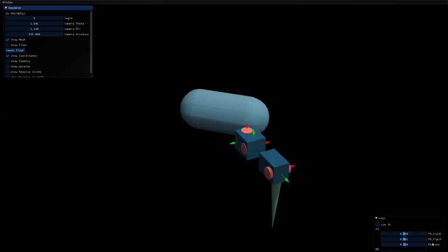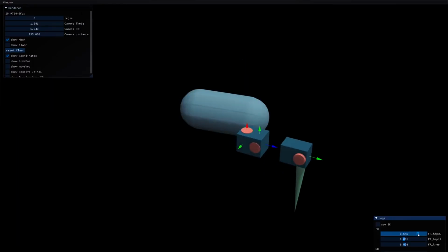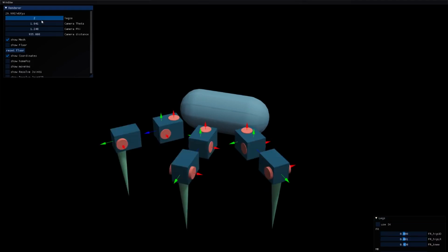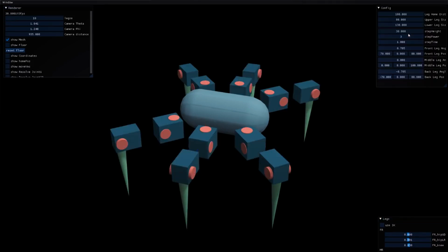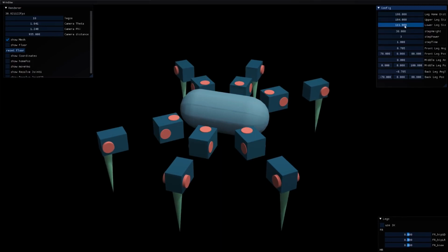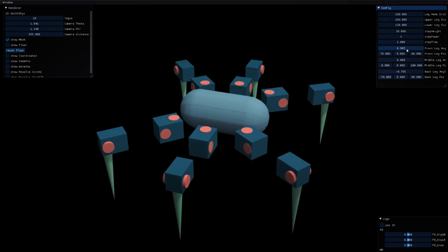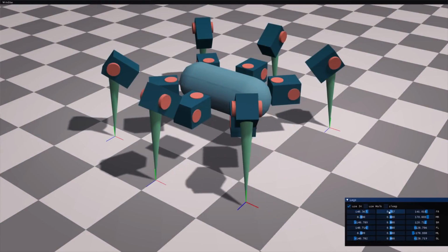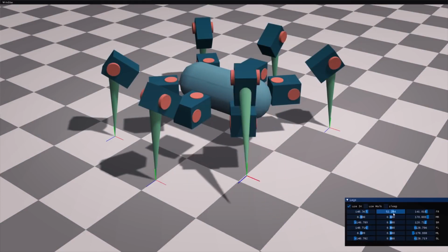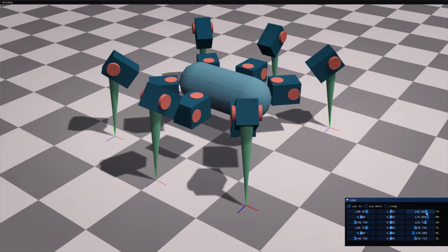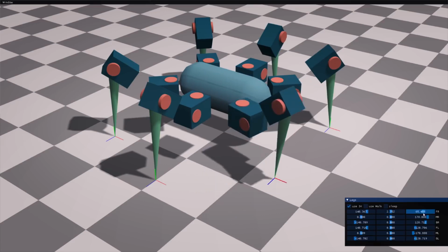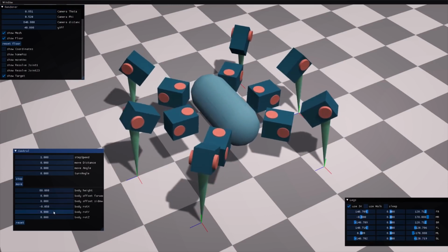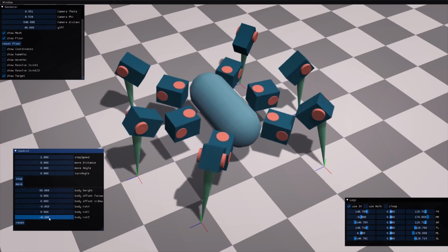Now, making a walking cycle with just adjusting the rotations of the motors is in theory possible, but that would be a very static and non-flexible thing. If I changed the length of a leg, I would need to start all over again. So here comes the next step in play, inverse kinematics. Instead of controlling the angles of the motor, you just control the end position of the leg and let the computer resolve the correct rotations for the motors. If you do that correctly, you end up with a very flexible model.